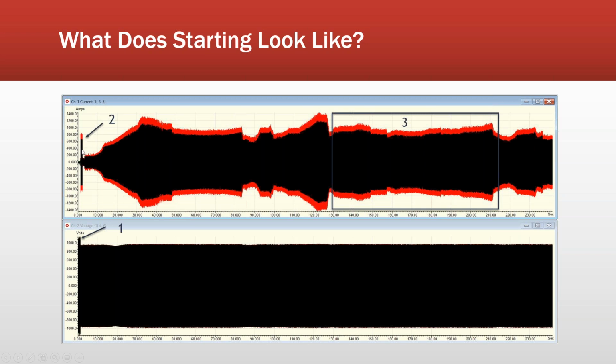Being an industrial type, we normally start our machines up and bring them up to speed. Very rarely do we start spinning something up to speed and then activate it, causing the entire system to shock. And for systems of this size, very rarely will you ever see us try to start something anywhere from 6 to 12 times in an hour. But that's what we see in wind. So a machine might be loaded and unloaded, cut in and cut out many times an hour. Insulation systems and mechanical issues don't last very long in those conditions. Now, that very long doesn't mean days.